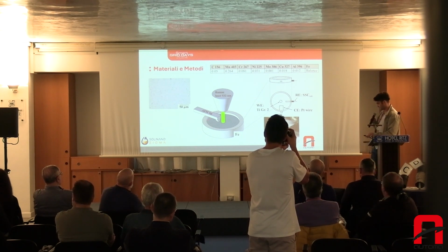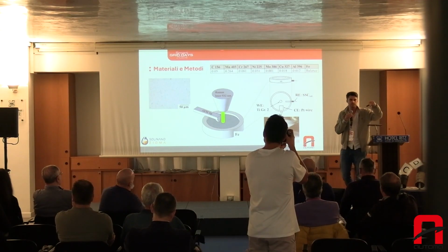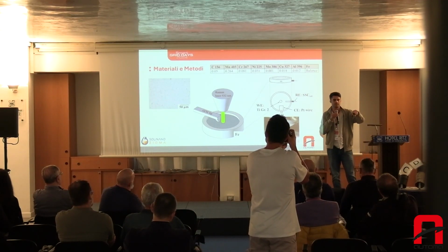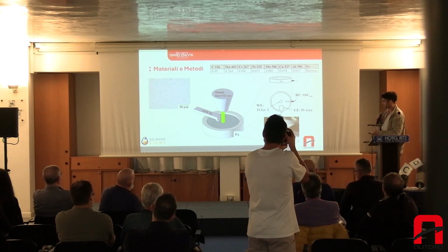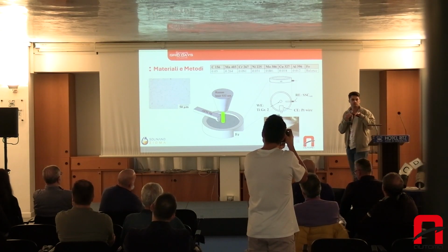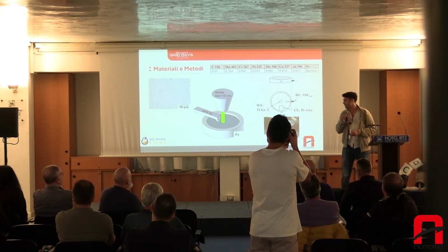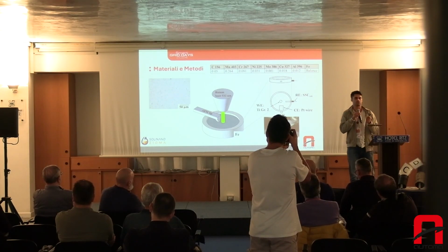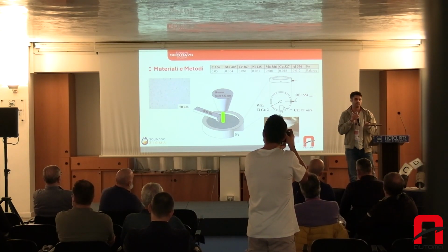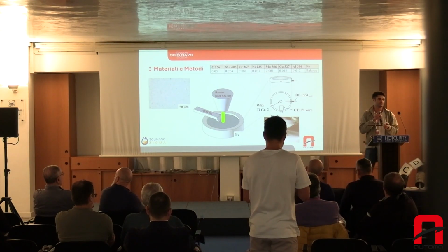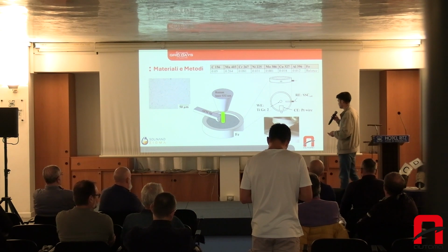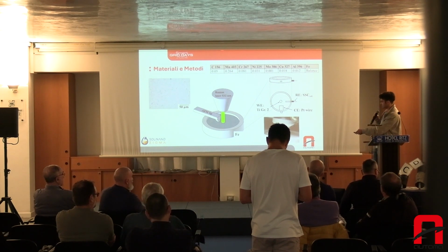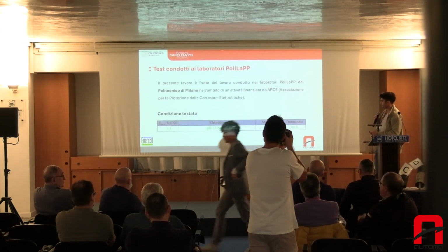You need to know how the surface is made up, so you need to use the atomic force microscope. It's like the tip of a record player, and the roughness profile enables us to have results. And then you have a laser. The laser is directed towards the steel, and the return beam is analyzed through a Raman spectrometer that tells us a lot in terms of what kind of substances developed.